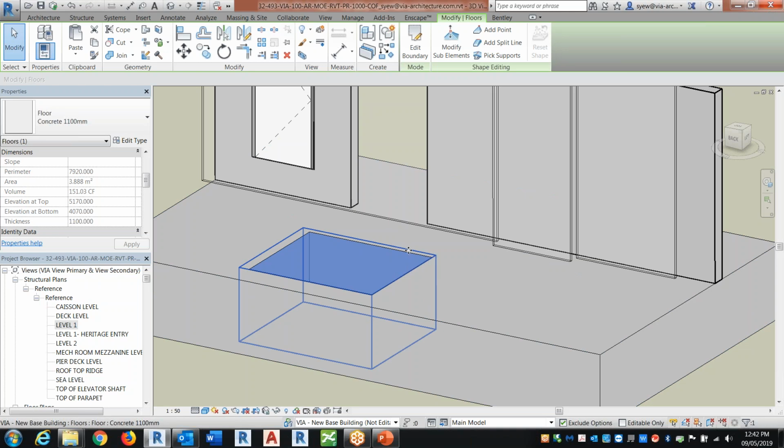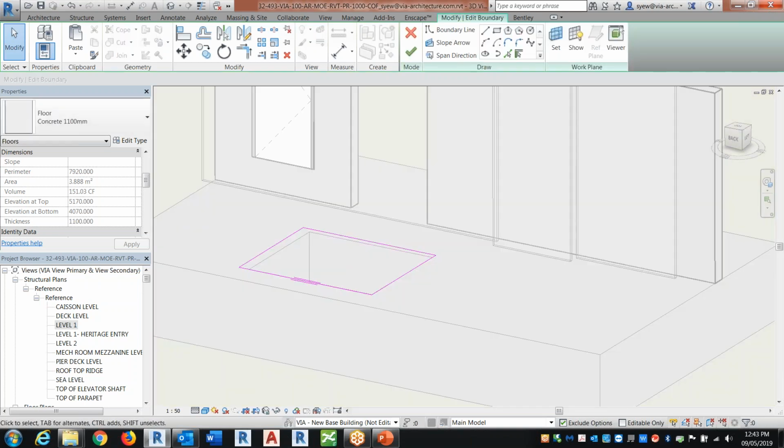So it's a complete reversal of, let's say you put an opening inside your wall, and if you demolish it, the hole is going to get filled in. But the floor is a complete opposite. So this is why I said you just have to be aware that this is how Revit operates. It's completely different from wall and floor. Floor shows up, that's exactly what you want. If you want the shaft to be demolished, you set the proper phase, and if you want something to fill in, then it will not cut into that particular new hole in a new construction.